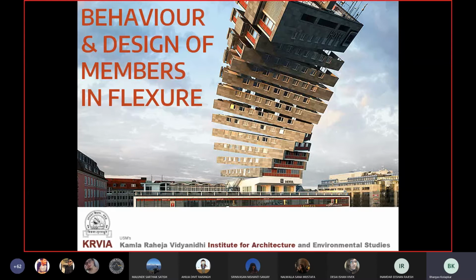So under the category of this definition, we'll have beams and slabs, which already have been answered. So the question is, what about the vertical members? Would columns or structural walls experience flexure? And yes, definitely buckling is a design criterion, and buckling is a different phenomenon. We'll get to what buckling is and how we deal with it. But as of now, we're talking about bending.